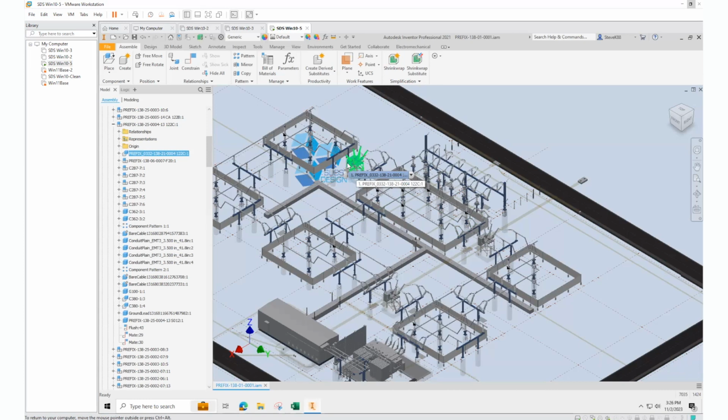If you pay attention to how Inventor works, open documents in session makes the model heavier. The number of occurrences, I can have 70,000 occurrences and not have a real issue with my model, but it's the open documents in session. If I get over 3,000, it starts slowing down. I'm not saying that's a limit by any means, but it starts slowing down. I've seen people with 7,000, but it's pretty slow. So I'm trying to lower that number.